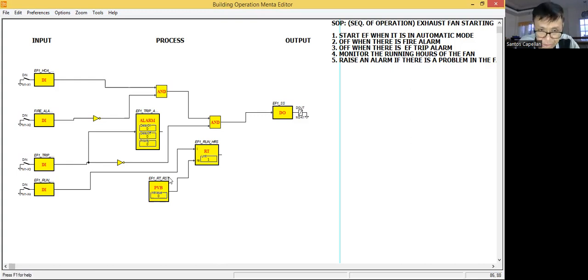software points. Now when you say software points, these are not associated with cable. So we are generating these points inside our control logic program. When we make this public, it will be available in our server, so that we can use it in binding our graphic. Now let's save it.